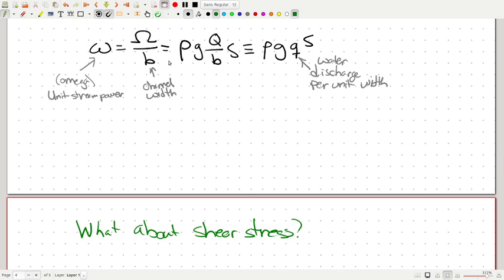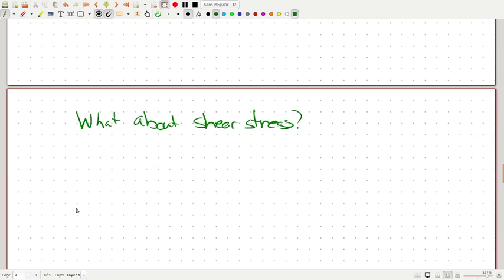And so I'm going to start out with this equation that we have right up above for unit stream power. I'm going to rewrite it, and everything here is going to be green just so you can see when I post this PDF that this is all one big aside, and we can get back to talking about stream power if you want. But this, I think, for those of us who like to have a self-consistent way of thinking about these problems, I want to present this just because I feel like this is really helpful, at least to me, in linking these concepts together. So this little omega, which is unit stream power, is equal to rho g times q, discharge over channel width, times slope.